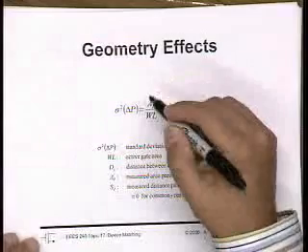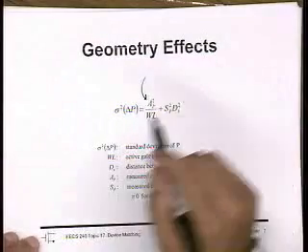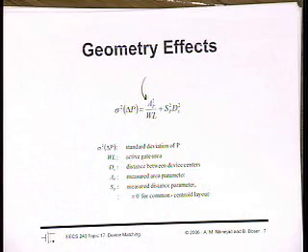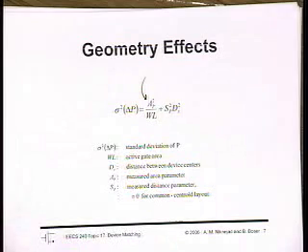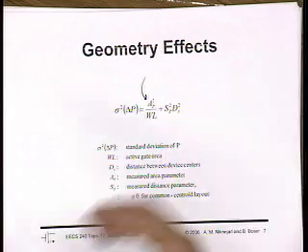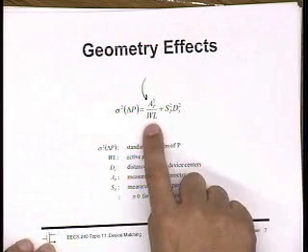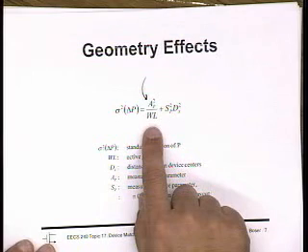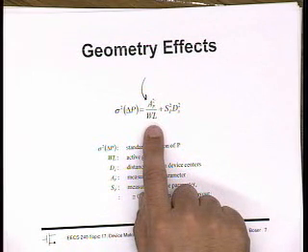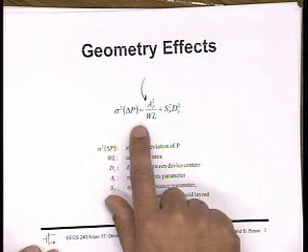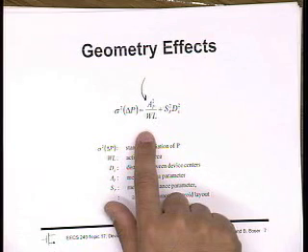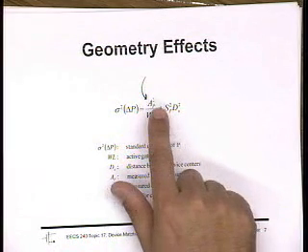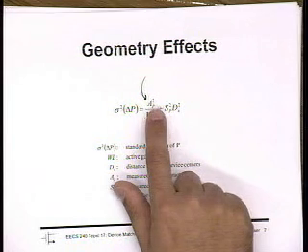The part that you don't control is this coefficient. So this AP is some process-dependent coefficient which tells you the scaling factor. If you're given a new technology and you have to characterize it, you can go measure the VT of 100 different devices with different W's and L's, and then fit the variation of VT to this equation. If you take the square root of this to get a voltage, the variation will fit 1 over square root of area very well, and the slope of that line is sometimes called the Pelgrom coefficient.